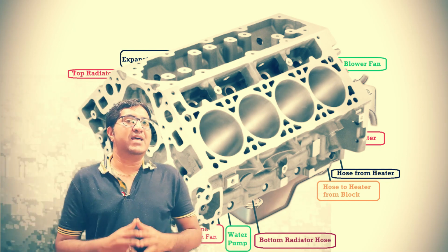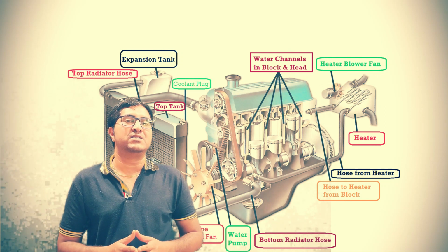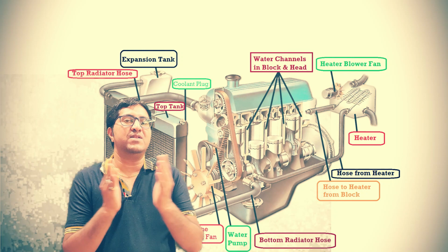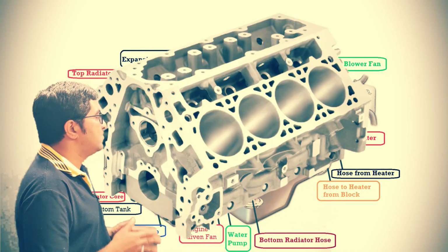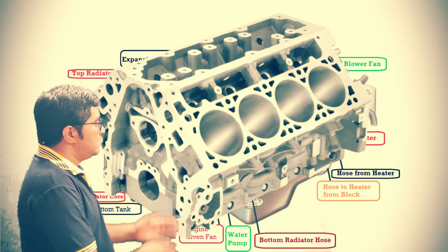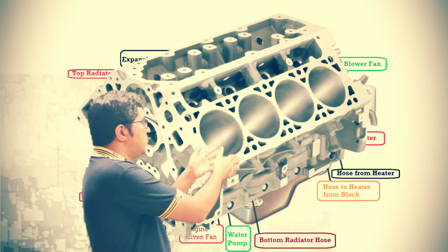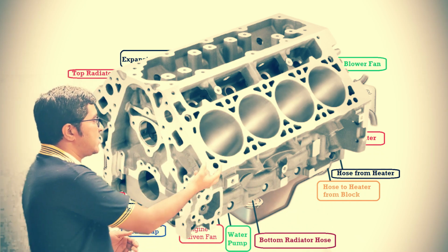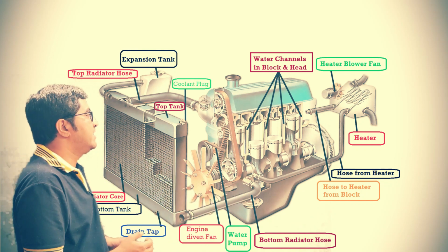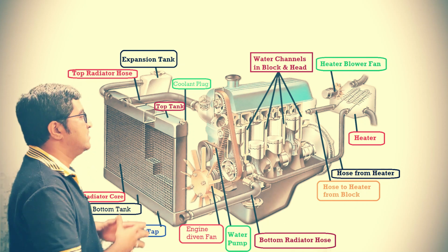As we know, in a racing car the operating temperature range is up to 2000 degrees Celsius. At this higher temperature, the piston will expand and seize inside the cylinder. So for that these water spacings are provided. The coolant will flow through this spacing or water jacket, absorb the extra heat from the engine body and reject it into the radiator. This type of arrangement is called the water cooling system for the engine.